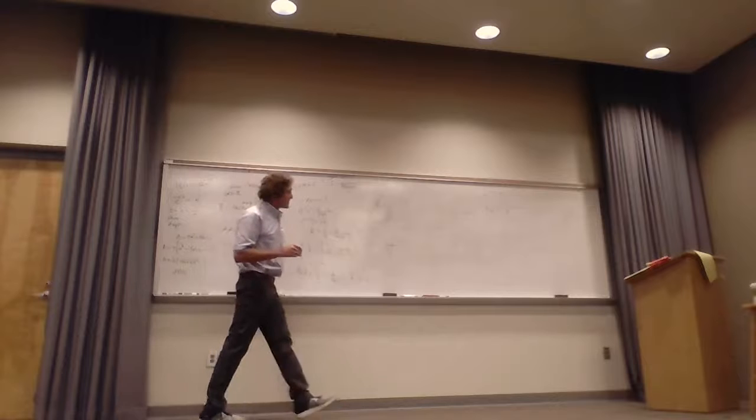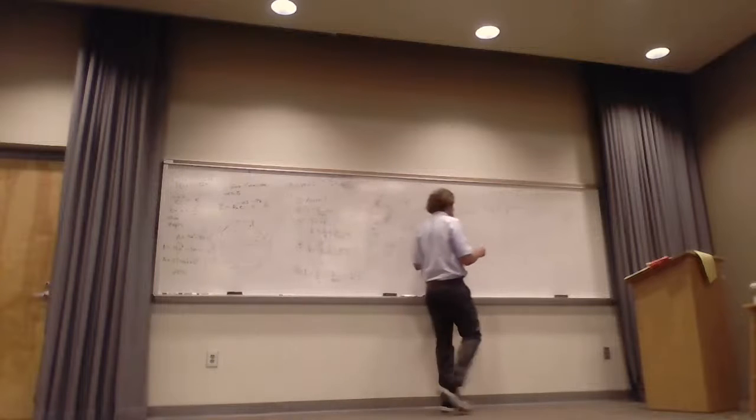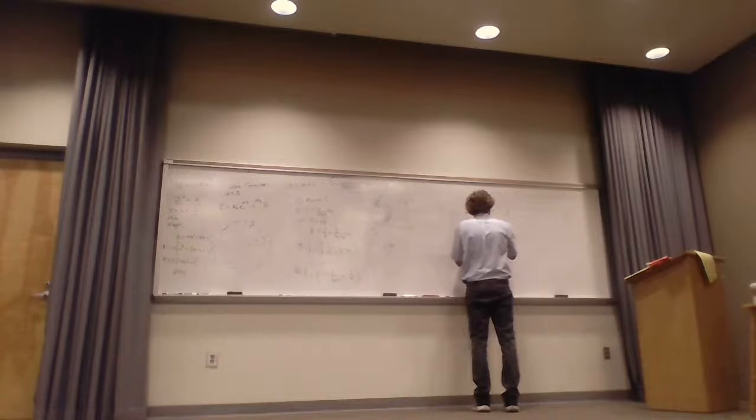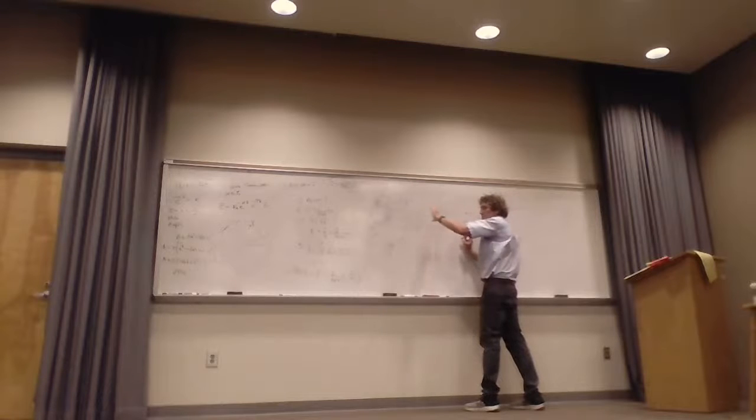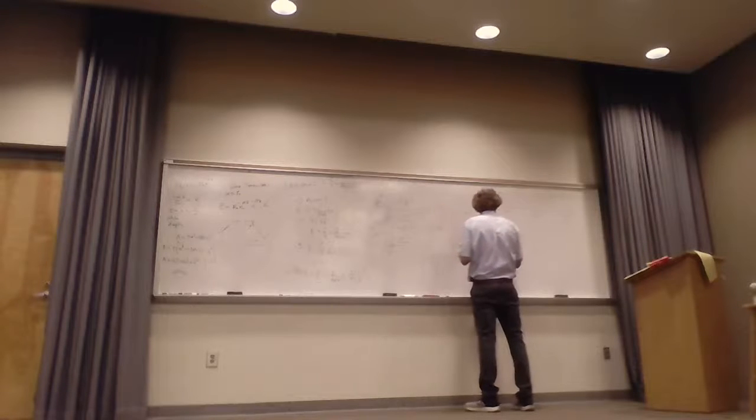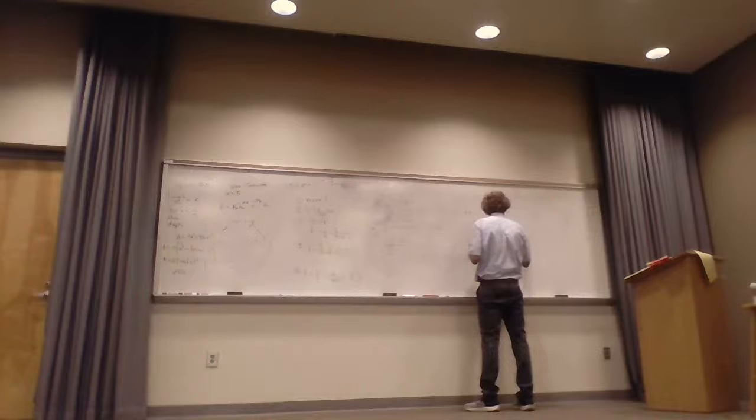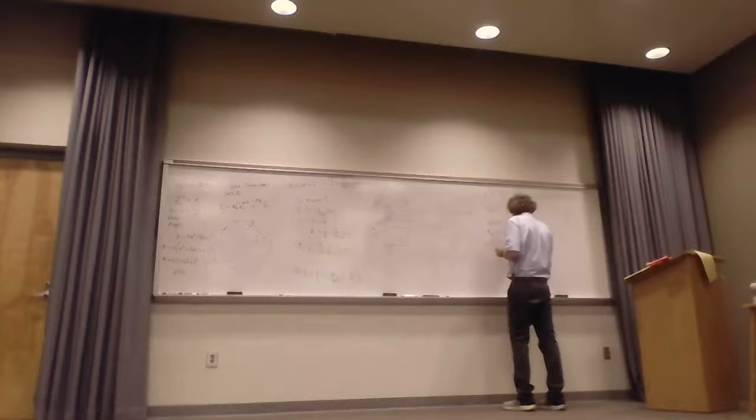And generally speaking, what they do is say this. For AC resistance, if the skin depth is much less than A, which is a lot of times the case, then the resistance of anything with a constant cross-section is given as the length over sigma times area, always that, but then they approximate the area as 2 pi A skin depth.